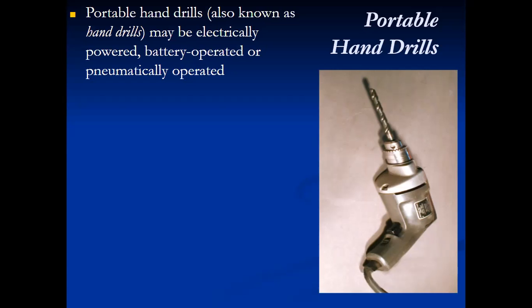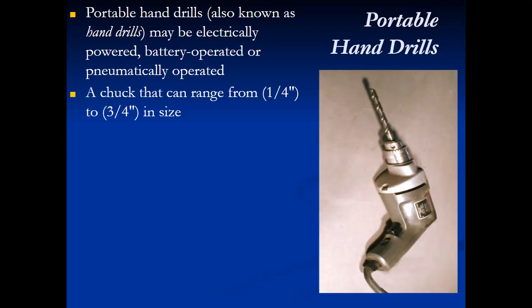That definitely works. Yeah, ours are definitely a little newer than the one in this picture here. But yeah, we can operate air drills. We can operate battery operated and electric drills in here as well. On these drills, the chucks are going to range from 1/4 inch to 3/4 inch in size. If we do have a larger drill in here, it's going to have 2 handles on it, and that's for running bigger bits so you can support it.